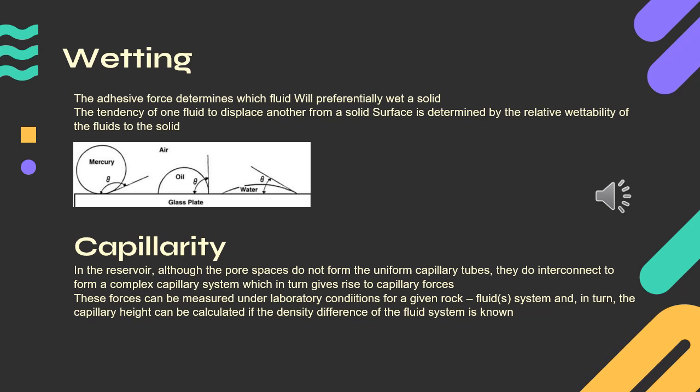In the reservoir, although the pore spaces do not form uniform capillary tubes, they do interconnect to form a complex capillary system, which in turn gives rise to capillary forces. These forces can be measured under laboratory conditions for a given rock and fluid system, and in turn the capillary height can be calculated if the density of the fluid system is known.